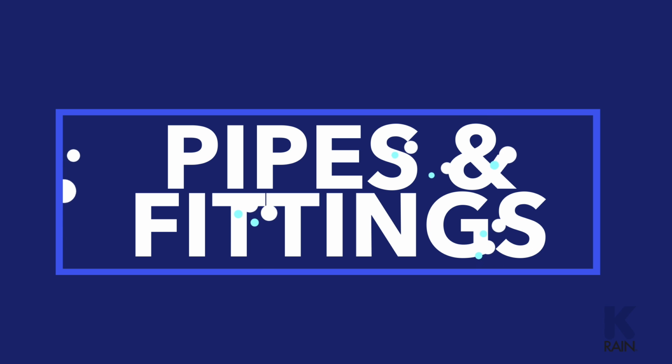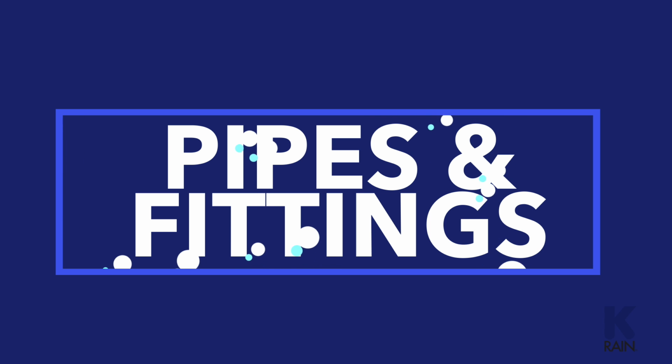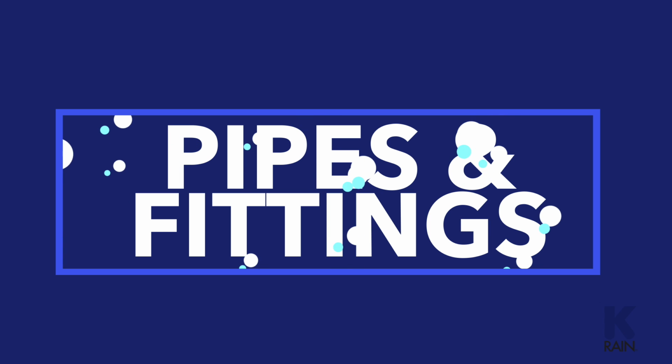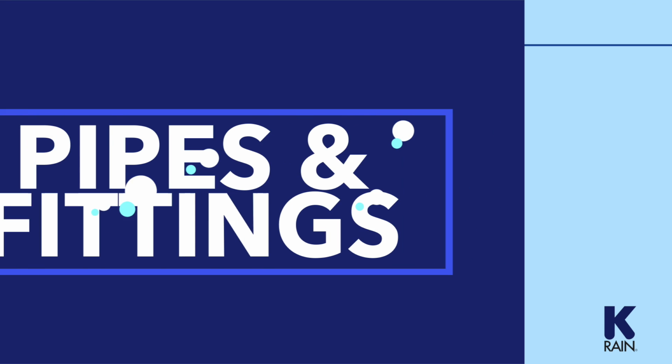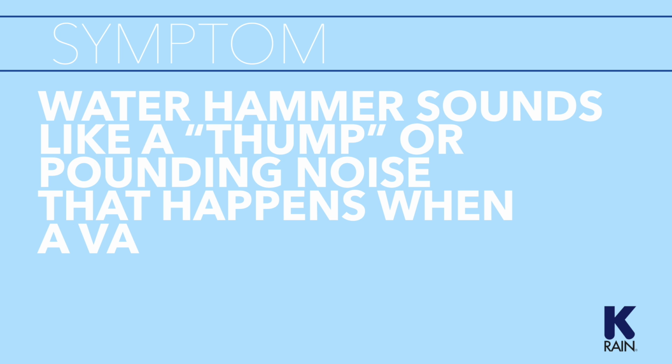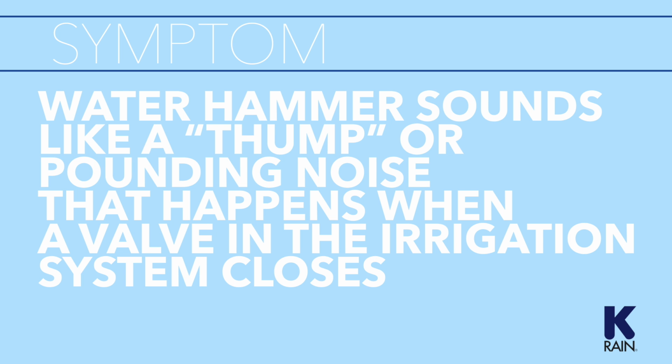The two main problems associated with pipe and fittings are leaks and water hammer. We'll start by talking about water hammer. Symptom: water hammer sounds like a thump or pounding noise that happens when a valve in the irrigation system closes.